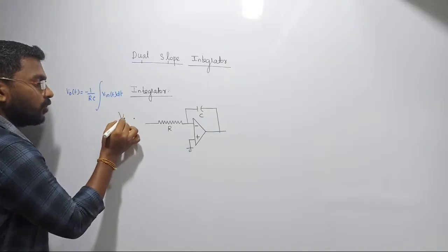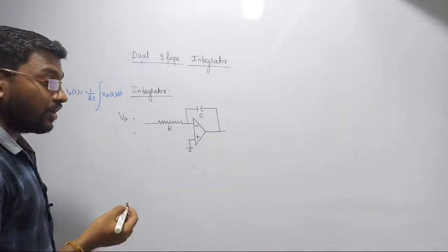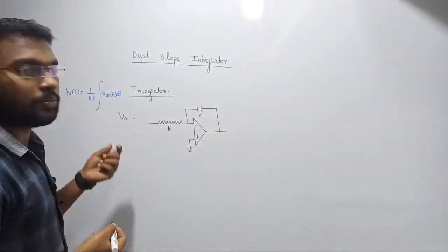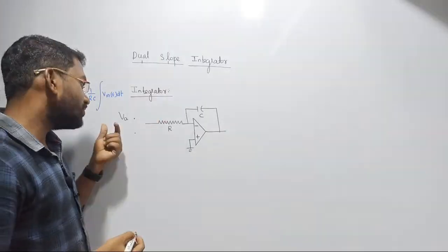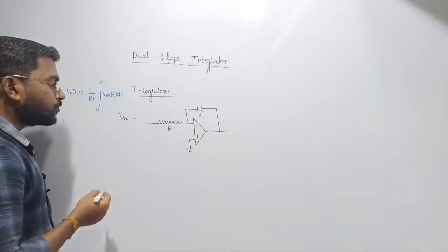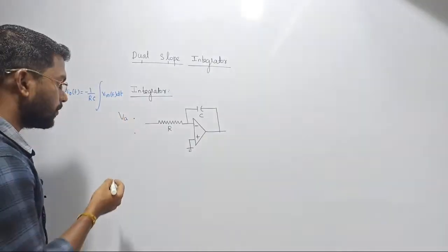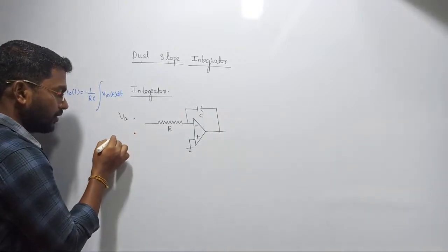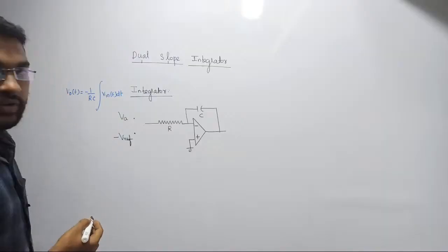One is the input voltage. This is simply called the analog input voltage, because we are designing what? An analog to digital converter. So your input voltage is simply called analog voltage. Don't think too much. I have some input voltage and I would like to transform it into the electrical domain. That's all. And here I am going to use a single pole double throw switch once again because there is some purpose. And here I am going to use minus V reference.